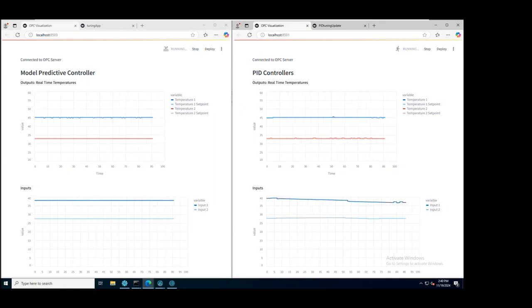And long before the craze around machine learning, model predictive control emerged as a closed-loop control technology in the 1970s under the name of dynamic matrix control from Shell. And it has a few elements which make it quite a bit different to PID control, or proportional integral derivative control, which is, of course, the most widely and most popular form of closed-loop control in industry today.